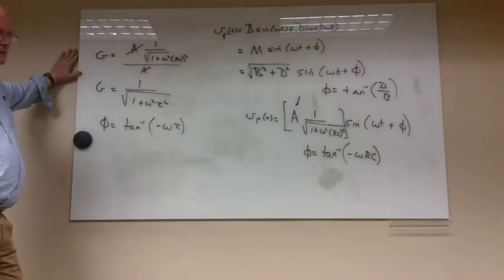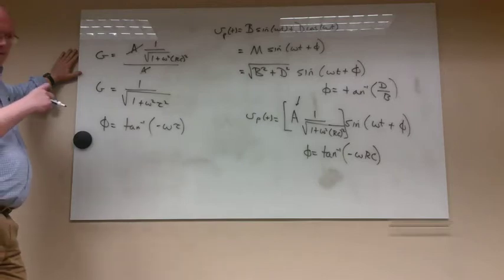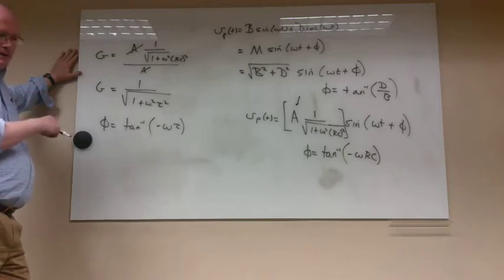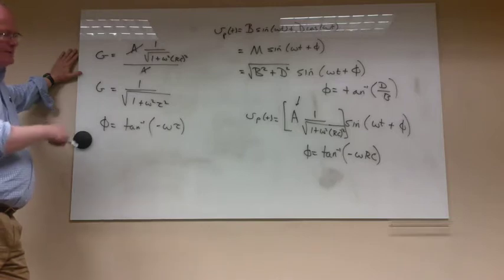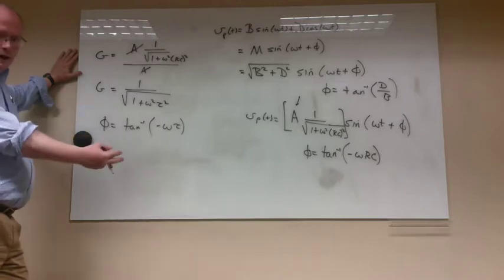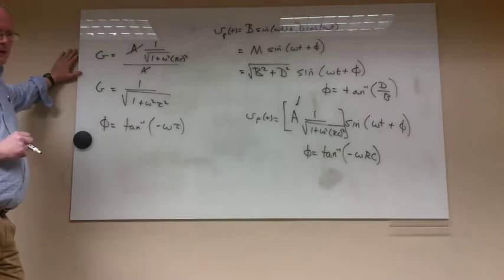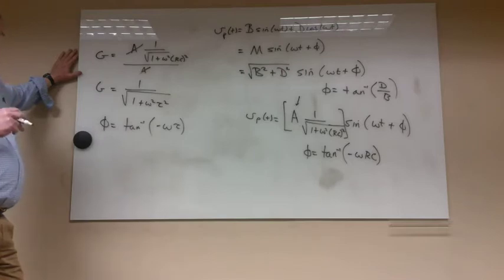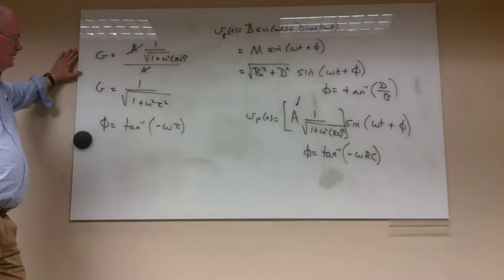It also is particular to a situation like the RC filter, where if you put in 5 volts as an input, say a step of 5 volts, you will get 5 volts out. I'm saying that because the ratio at steady state for a constant input is 1 to 1. You put in 5 volts, you get 5 volts out at steady state for a constant input.